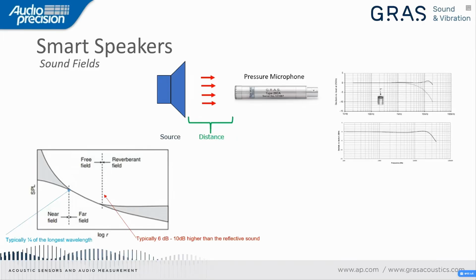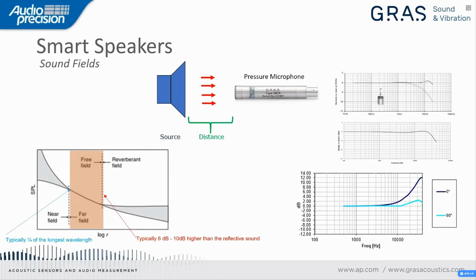But if we move the pressure microphone away from our sound source, so we go from the pressure field to the free field, then something will happen, because we will start building up pressure at higher frequencies in front of the microphone, because the microphone will disturb the field in which we are operating.